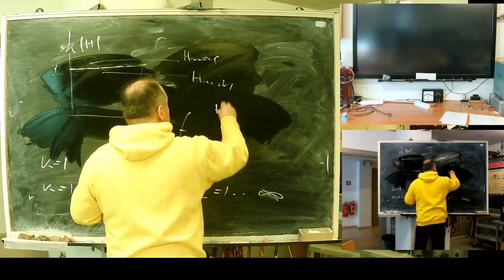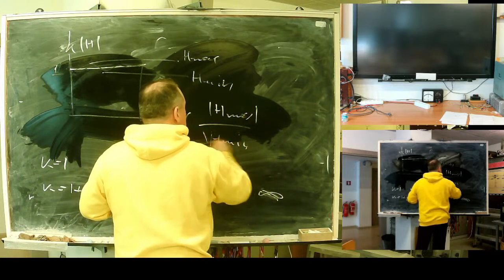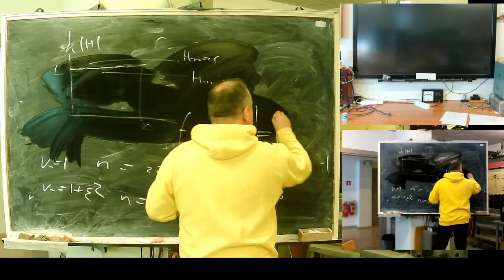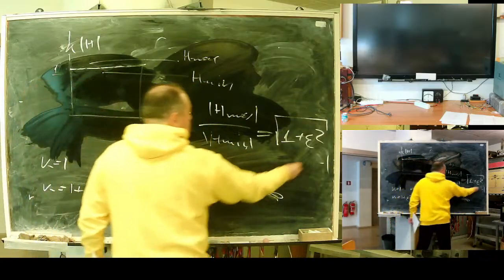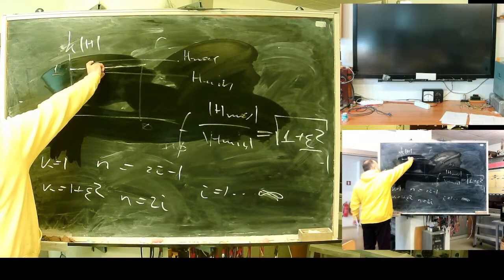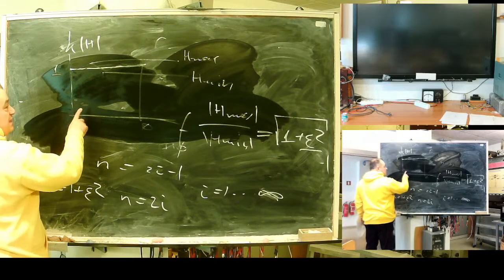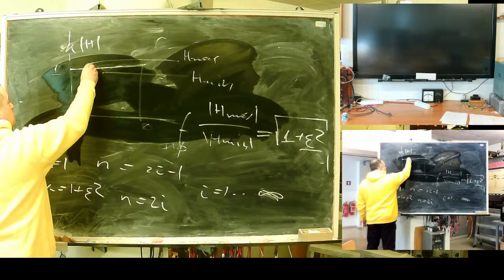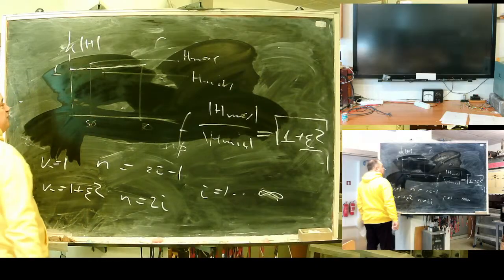This ratio for a Chebyshev filter equals 1 plus epsilon squared. So with selection of this parameter, you can select non-uniformity. I can tell one thing, if you use Chebyshev design, you can do one trick. You can play with factors. So let's say this will be at 50 Hz.